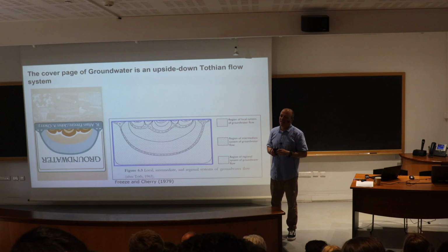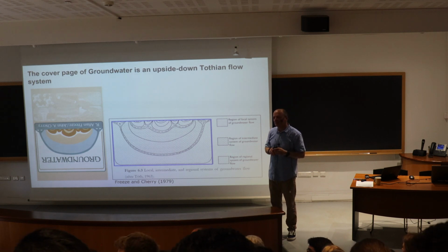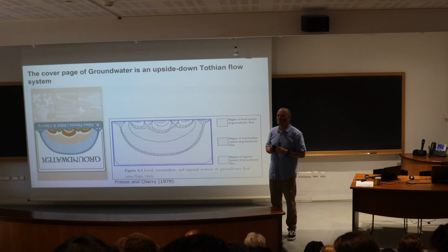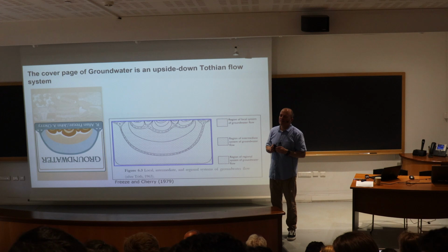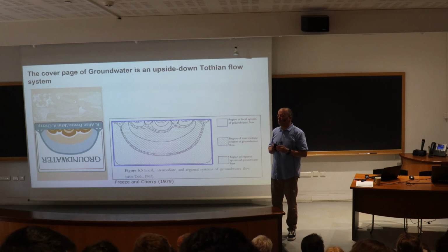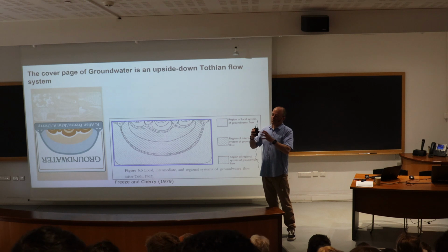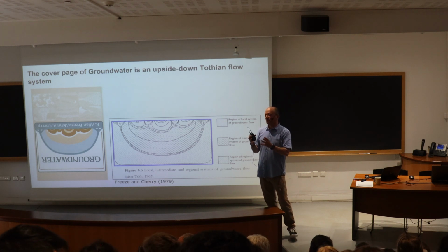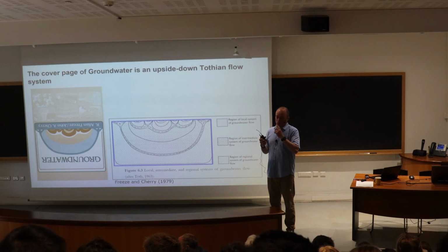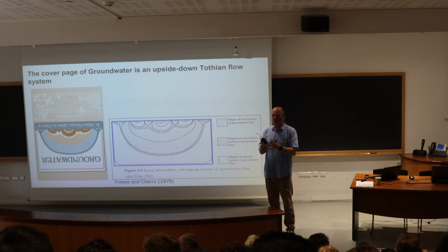Yes? I had a question about when you talked about the flow velocities, the Darcy velocity divided by porosity, but porosity can also have dead end curves. So how do you show that without having it incorrectly account for the dead end curves? Yeah, I mentioned that porosity, its definition, is for the whole volume of porous medium. It's the volume of pores or voids for the whole volume of porous medium. And you could go out in the lab and measure that.